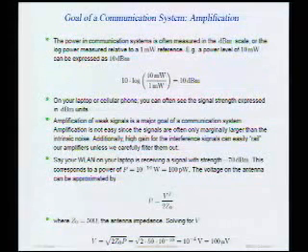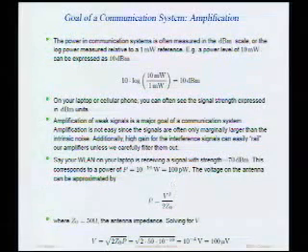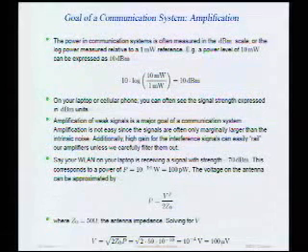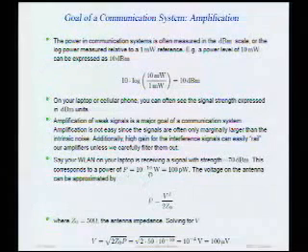Now, it's good to know that because almost all the communication equipment that you carry around with you, perhaps even today, has a little signal strength indicator, which is an estimate of how strong the signal is that's coming in. And if you look at your wireless LAN, you might find that a typical signal strength might be, let's say, minus 70 dBm. So if we take minus 70 dBm and translate that into watts, well, that's 10 to the minus 10 watts, or 100 picowatts. It's not much power, is it?